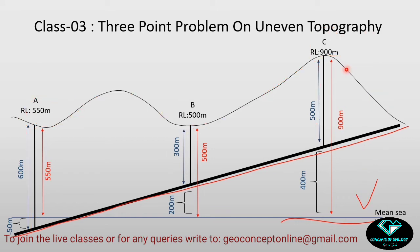So the data we are having now are the RL value of this point C and the depth of the borehole. By using these data we will find out the attitude of this target bed. But the problem here is the depth value of the borehole is a variable factor, because I am measuring the borehole depth from this topography and the topography itself is a variable factor. The topography is not flat, it is varying with respect to the datum plane, that means my mean sea level. So when we solve the 3-point problem, we cannot use the depth data, because the depth data is a variable factor.